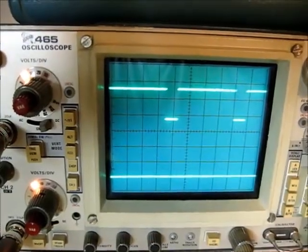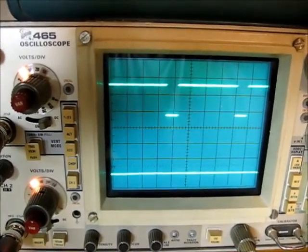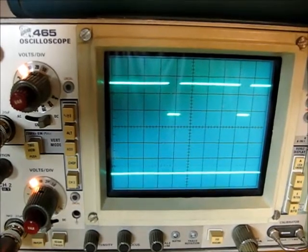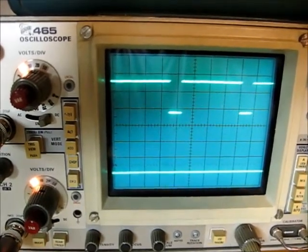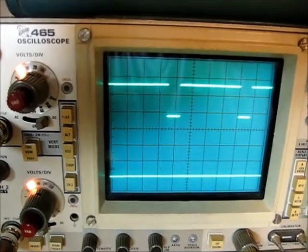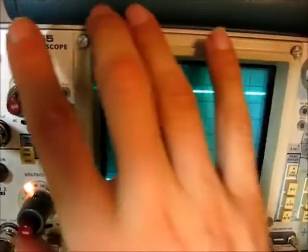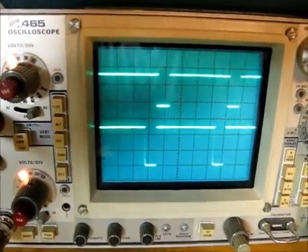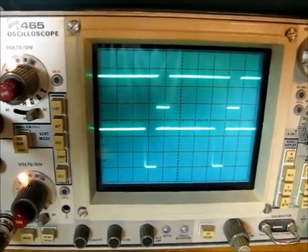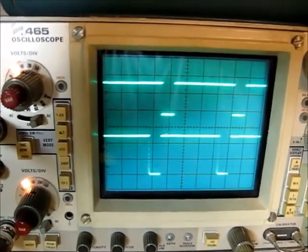Okay, upper waveform, that's the multiplex signal. That low part in that waveform is actually ones of seconds output. The other 5 are high. Alright, and so we're going to turn on the lower waveform here, and that's a segment output. This particular one is the A segment that I have connected to.